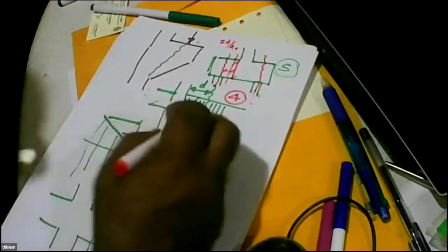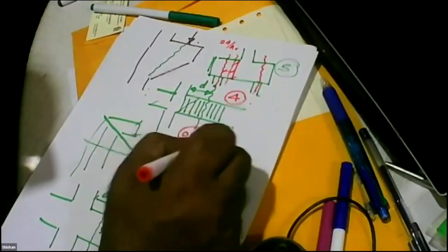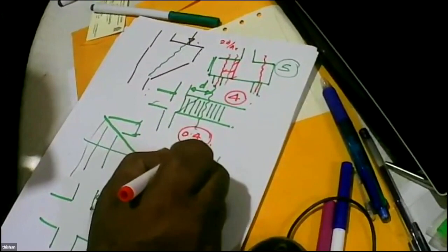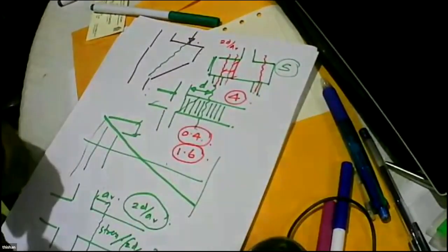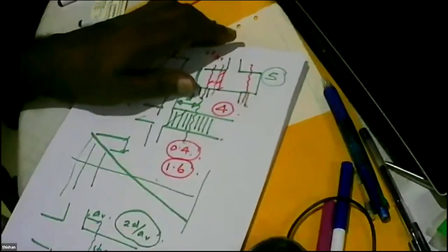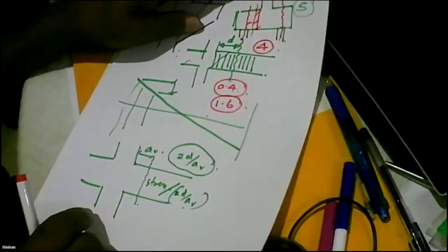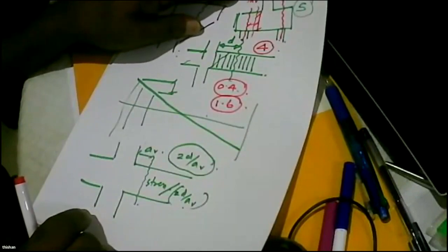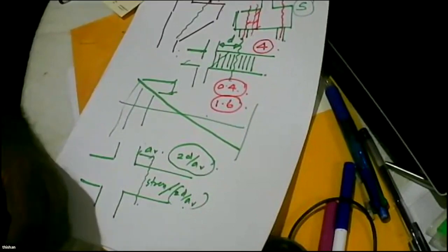So what is the shear stress of concrete? Something like 0.4 for thick sections. So this can be enhanced by 4 times, so it will go up to about 1.6. So instead of using the shear capacity as 0.4, you will be able to say the shear capacity is about 1.6. So that's how we make sure pile caps do not fail in punching shear.